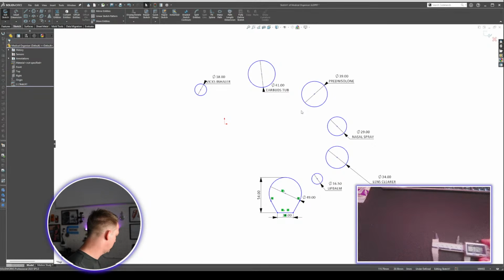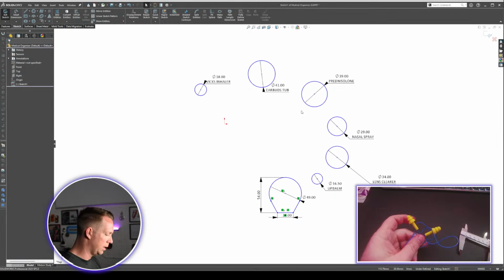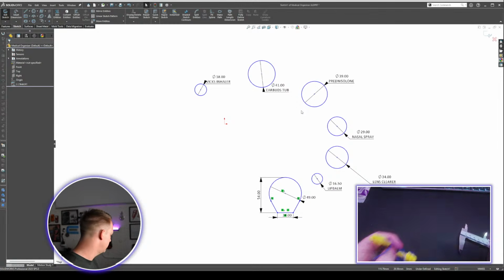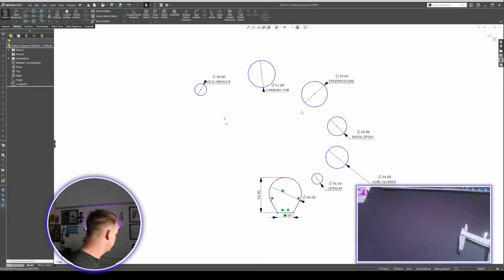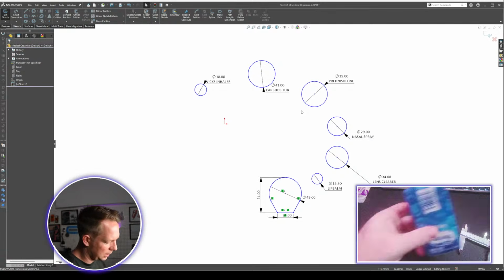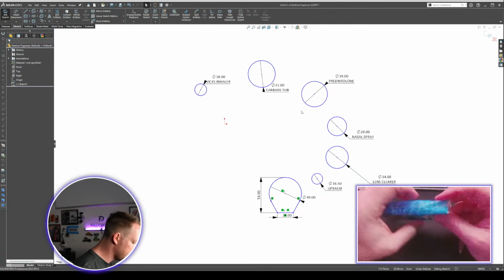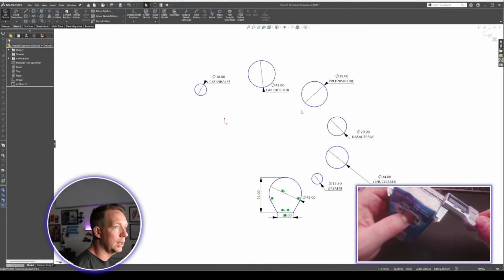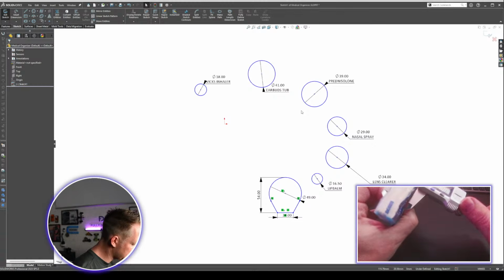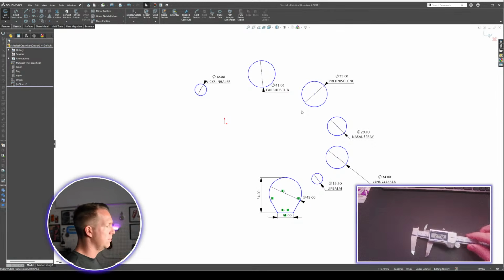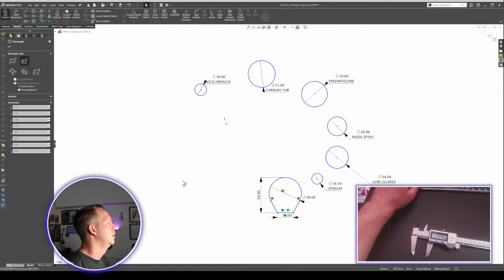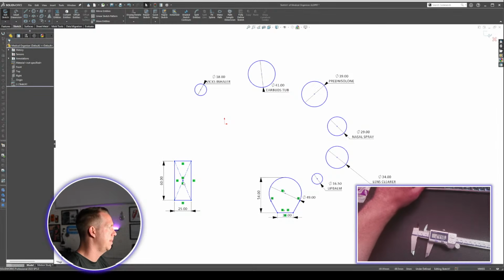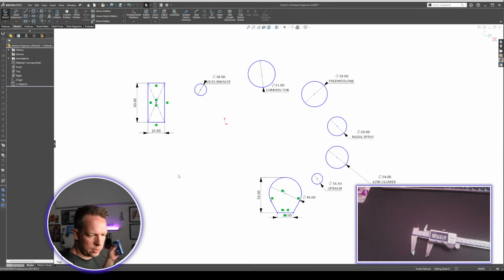All right, what else? So the earbuds here, I'm not actually going to create a shape for them because they'll just need an open pocket. So a bit of a plate or room to hold them. If I want to keep this little soft tissues pouch in a good space, what I can do here is just roughly do a rectangle. So 58 by 24 should be enough. But we could go a bit bigger, 60 by 25. All right, so that's our tissues.